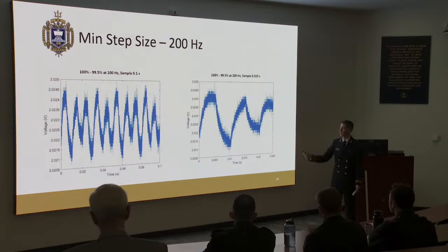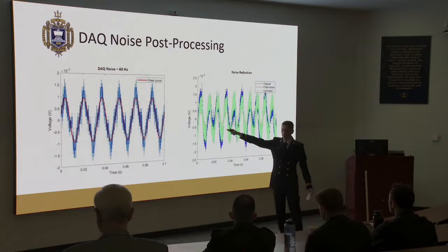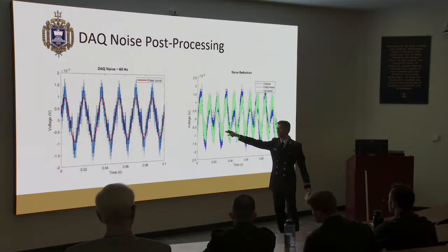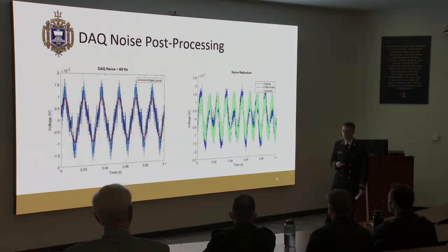So we had to measure the noise produced by the DAC with the PV cell unpowered. That's right here, and characterize it as a sine wave. That, coincidentally, is a 60 hertz sine wave, which, as you can imagine, is the same exact frequency as your power output, which, yeah, our DAC was messing us up.